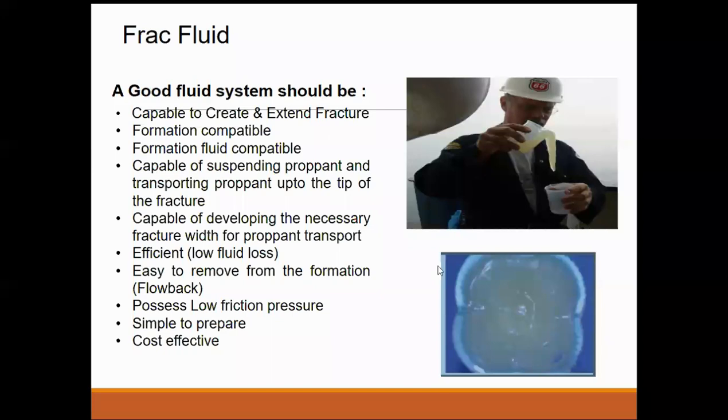It should be efficient, with low fluid loss, because fluid loss is bound to happen, because all matrices have some leak-off properties, and it will continue to leak off until you seal those leakages off. Okay, so it should have leak-off properties or fluid loss control properties. Okay, it should be easy to remove from the formation.